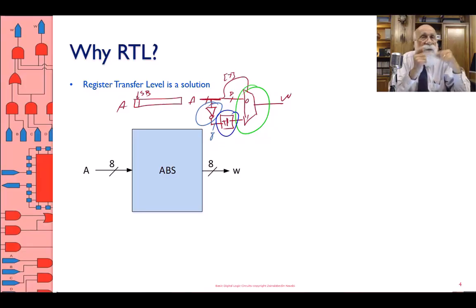And then just these wordings I turned into components. Selecting is multiplexing. Complementing, obviously, is using inverters. And then plus 1, I said, well, plus 1 shouldn't be that difficult. So I turned my more complex problem into some subcomponents.